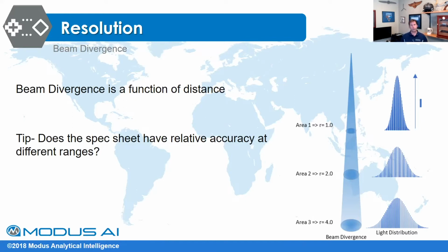But when we're dealing with these smaller drone sensors, you're not dealing with the types of optics that you're going to have with an aviation model. And the heads are going to be a little bit different. There's still some really good heads out there that are going to give you survey grade material, but you just have to be aware that your point density or your point spacing or your spot size is going to change, and that's going to vary what results you're going to get.